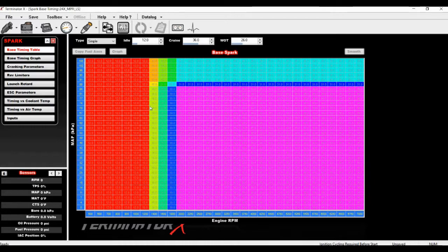It's too sharp right here. It's way too sharp right here, and what ends up happening is the thing will just buck like crazy because you're seeing these massive increases in cylinder pressure because you're flirting all over these ranges of spark timing, and it goes high and then it bucks and then it shuts off and it goes low, and it's a horrible situation. Don't do it.